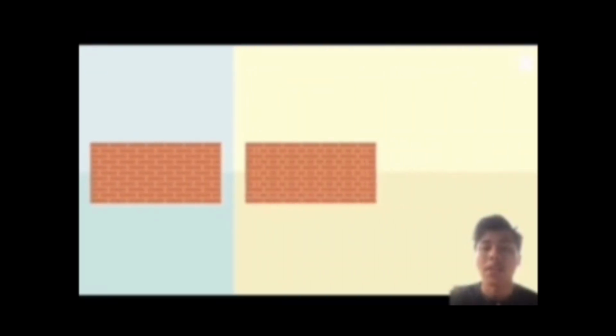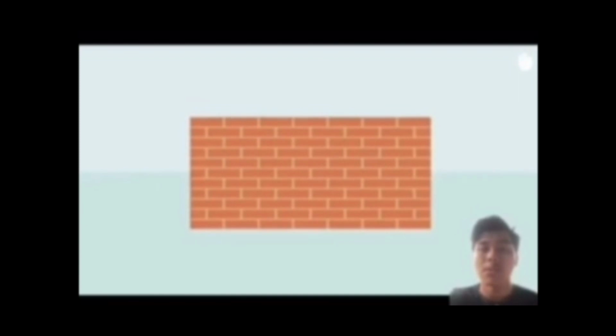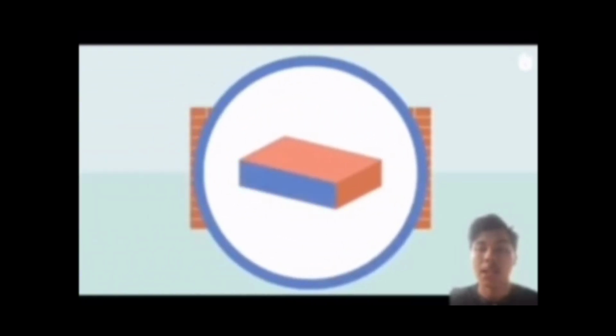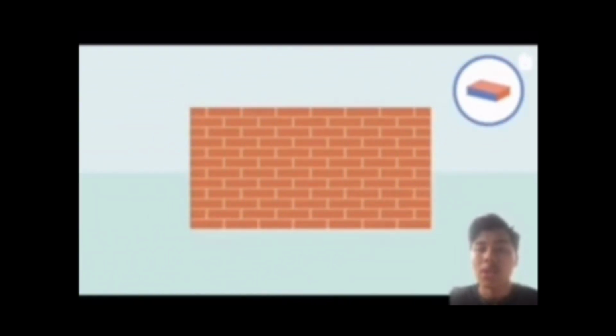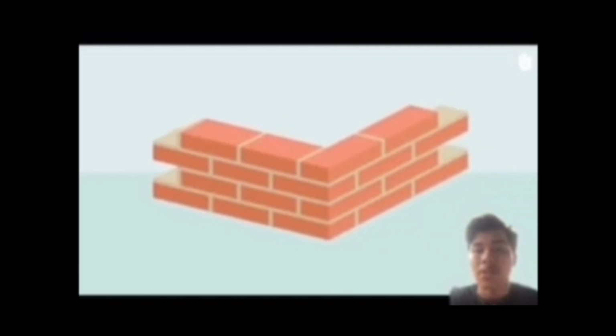When the base is horizontal, the bubble rests at the center of the graduated scale, which is engraved on the glass. To use the spirit level, place it on the surface whose level you would like to check. Wait for the bubble to settle and ensure that it is properly centered in the tube. If the bubble is not centered, make adjustments until it indicates a level surface. You can do this by varying the thickness of mortar or by applying pressure on the brick with your hands or a trowel. Change the position of the spirit level to make sure that it conveys an accurate reading.